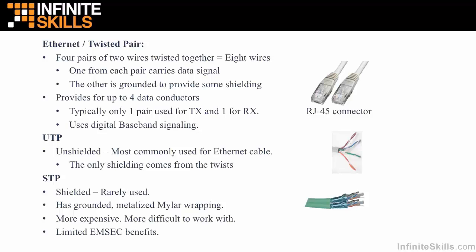And it helps to allow the data run, the cable length, to be greater, and we can still have enough signal at the end of the cable to understand what the signal is. So we use this twisted pair cable for our Ethernet networks. We notice that the connector at the endpoint has 8 pins, and it's called an RJ45 connector. So those pins actually are what plug into the back of your computer in the network interface card and plug into the wall jack, which is an Ethernet cable behind the wall, but it's the female portion of this RJ45 connector. And then, of course, those 8 wires connect to 8 pins that are part of this RJ45 connector.